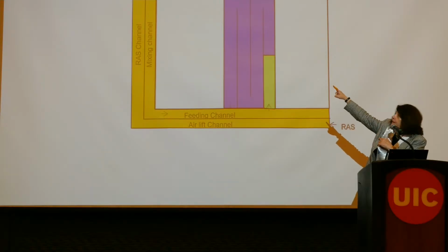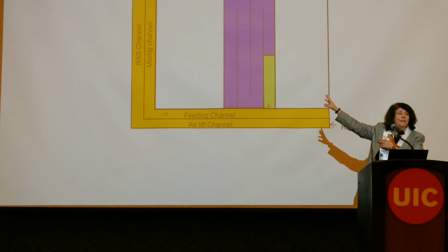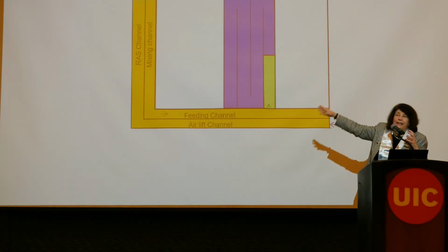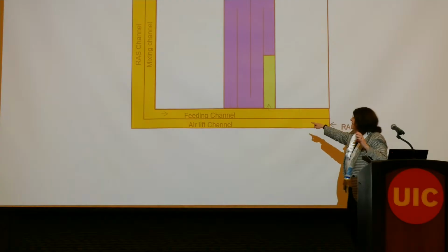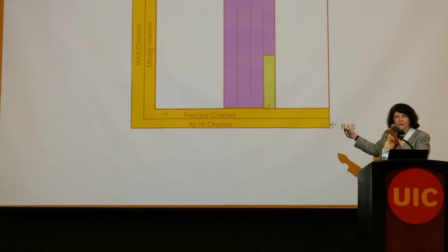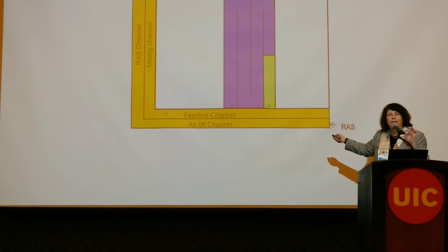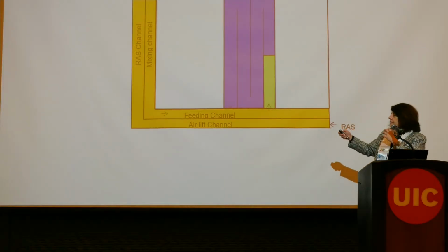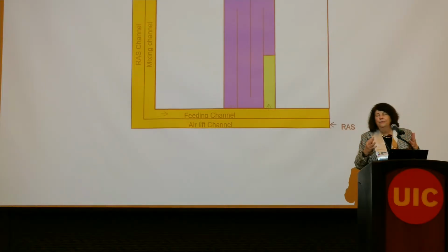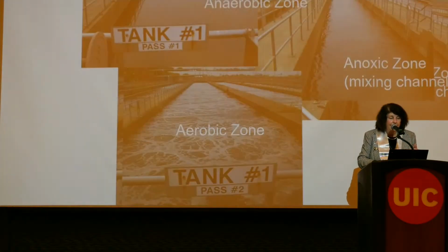The primary effluent is the PE. The mixing channel is where primary effluent mixes with the return sludge, removing the oxygen off the nitrate. So when that's fully denitrified, in the plant there are 4 aeration batteries, and the 4 aeration batteries have 8 4-pass aeration tanks with an anaerobic zone where the bugs starve of oxygen and take up phosphorus, and we're pretty reliable at 0.2 or 0.3 milligram per liter phosphorus.